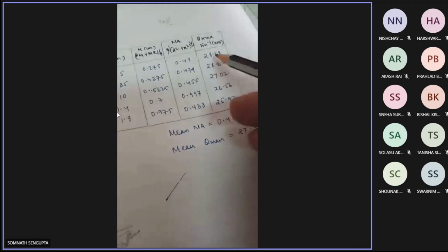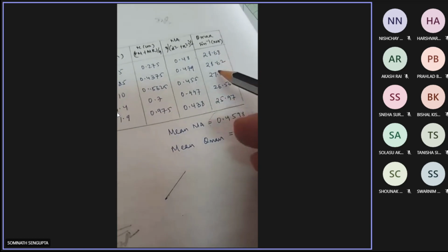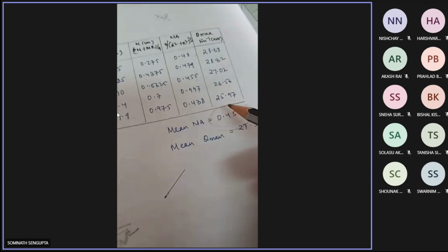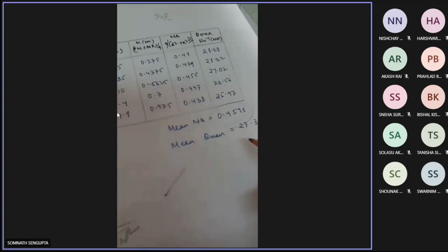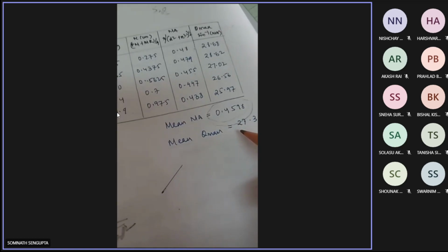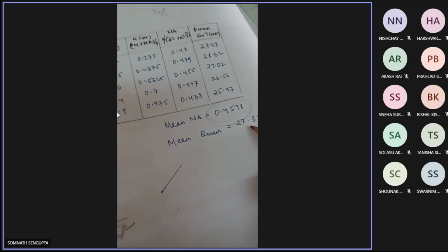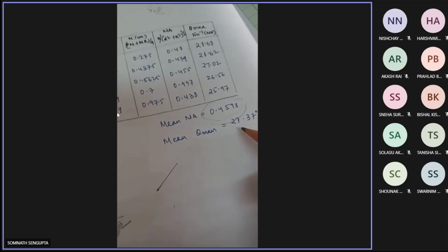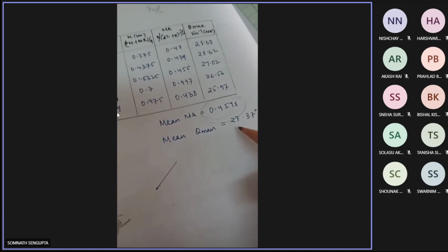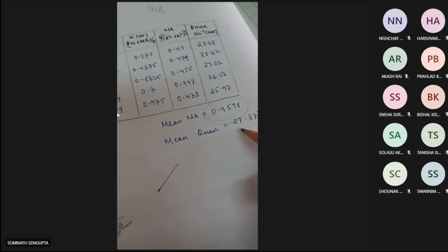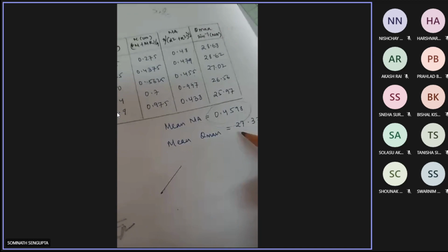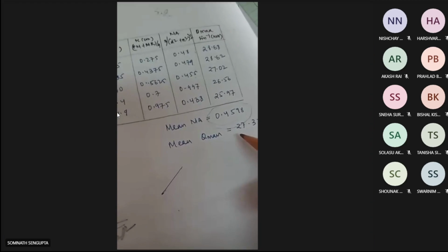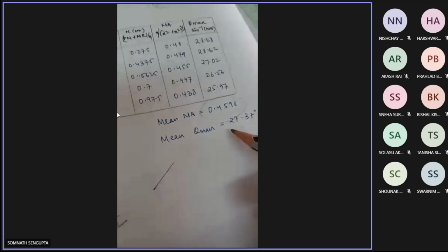And at the same time, you calculate the theta 0 max, that is acceptance angle. And this acceptance angle is coming near about 27 degree, or within 30 degree from the axis. So this is the overall process of calculating the numerical aperture.